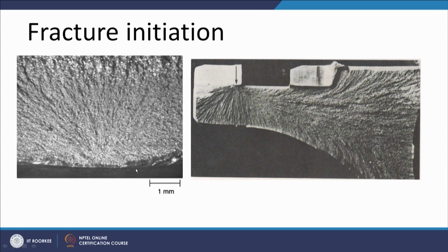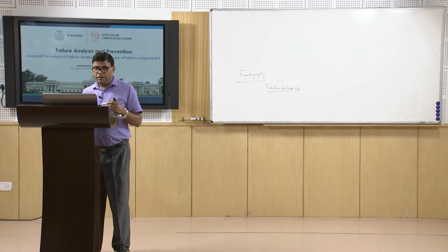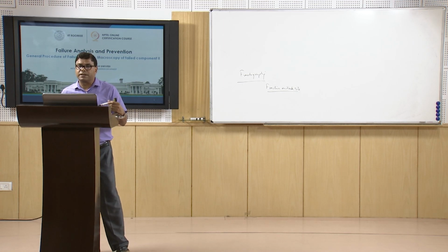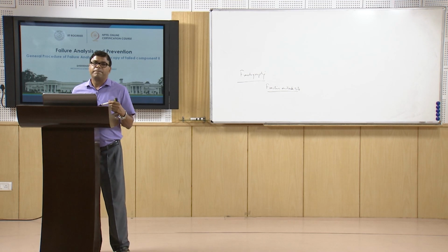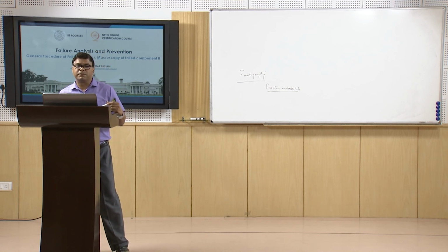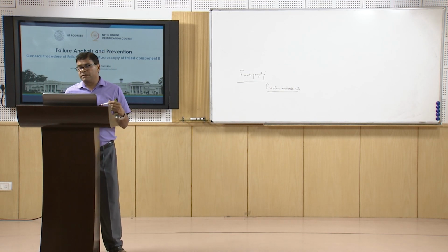to see why the fracture has initiated from this zone, whether there was some kind of crack or some kind of weakness in the mechanical properties or some other reason, like residual stresses present at that location. So, definitely there must be some reason why the fracture has initiated from that location, and that should be investigated in order to find the possible cause of the fracture.